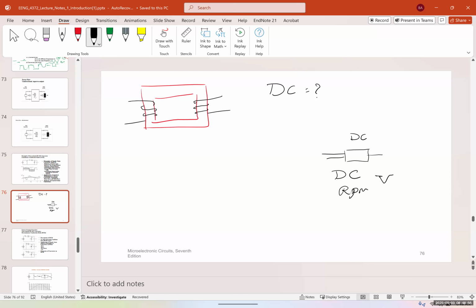By controlling its voltage. Yes. For an AC motor, you have to control its frequency, for a synchronous motor. For DC, increasing the voltage increases the speed, and decreasing the voltage decreases the speed. Okay. So for a DC motor, you may have had experience controlling it by simply changing the voltage. So how could I change the voltage on the motor of an RC car?